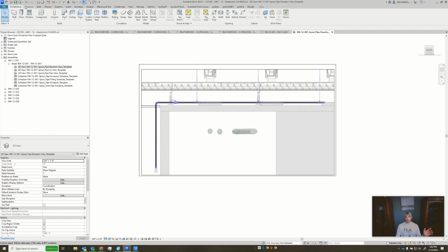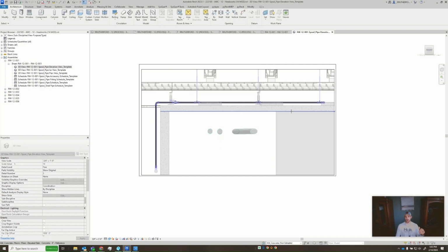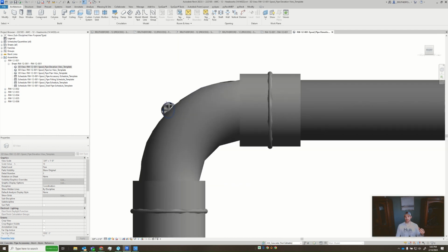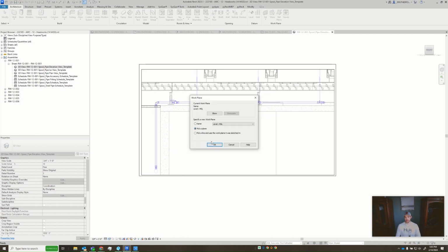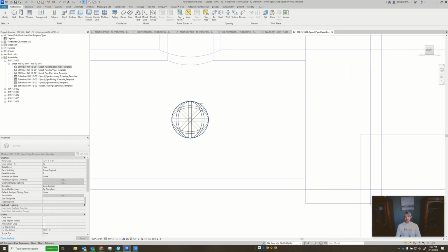So you can go to the architectural or structural tab. I believe you can also do it on a couple others, but for the most part, I'd stick with the architectural. It's the first one there. Go to set and a work plane and pick a plane. This is another instance of where those atoms come in handy. So I can zoom in and I know there's an atom here that I can work with, but in case you don't see them, go ahead, go to wireframe, and again, at your fittings, you will find the atoms if it's properly been done in the prefab manager.